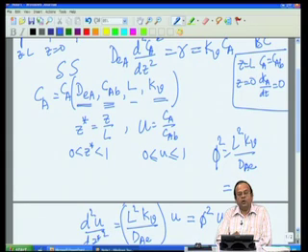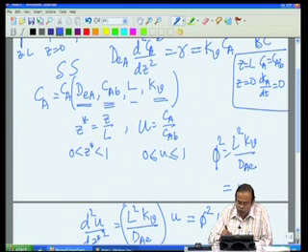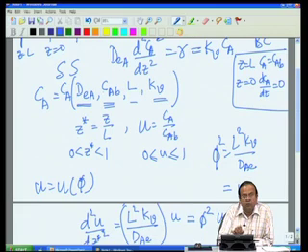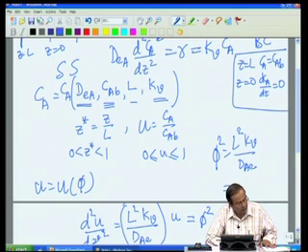So, various different values of L, kV and dAe, all of which result in phi square being equal to 1, have the same solution in terms of dimensionless quantity. Of course, in terms of dimensional quantities the solutions will differ, but all I need is to solve this equation for u. So, u is now only a function of phi instead of Ca being a function of these 4 variables. So, if I solve it for one value of phi, I have actually solved for several different values of these 4 parameters that we have.